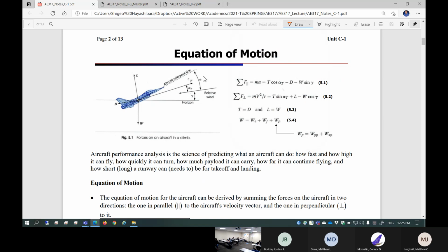So first of all, angle of attack, alpha, of course, you know that. This is basically the angle between the aircraft reference line, usually the chord if it's a cross-section of a wing. If it's a main wing, it's a chord. If it's the entire airplane, it's usually nose to tail. Nose to tail line, aircraft reference line, some kind of reference line having an angle against relative wind. It's called angle of attack, alpha.